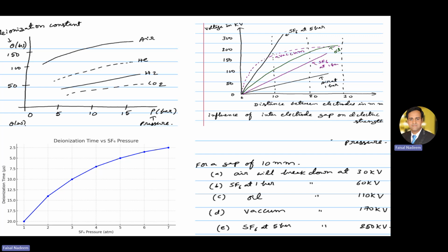So what is this breakdown value? The breakdown value basically indicates the value of the voltage, surrounding the contacts, at which the quenching material or dielectric available in the circuit breaker starts forming plasma.